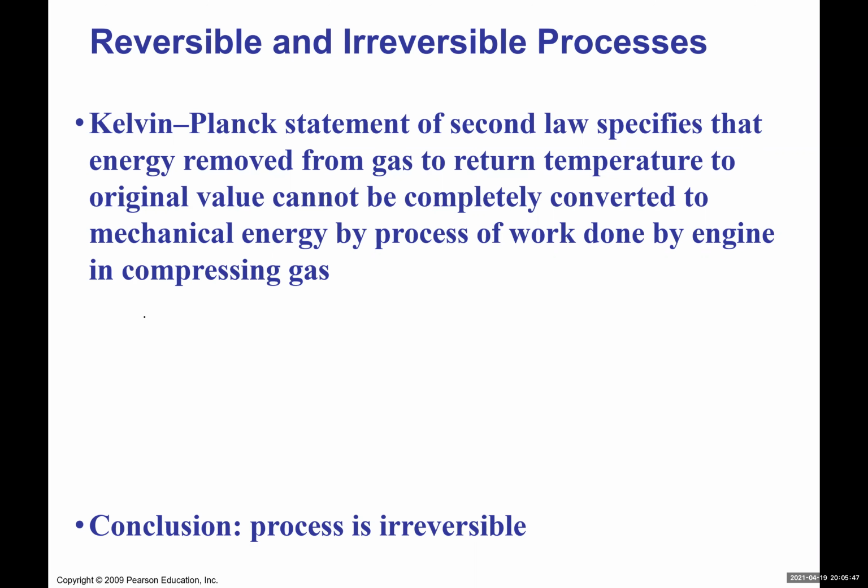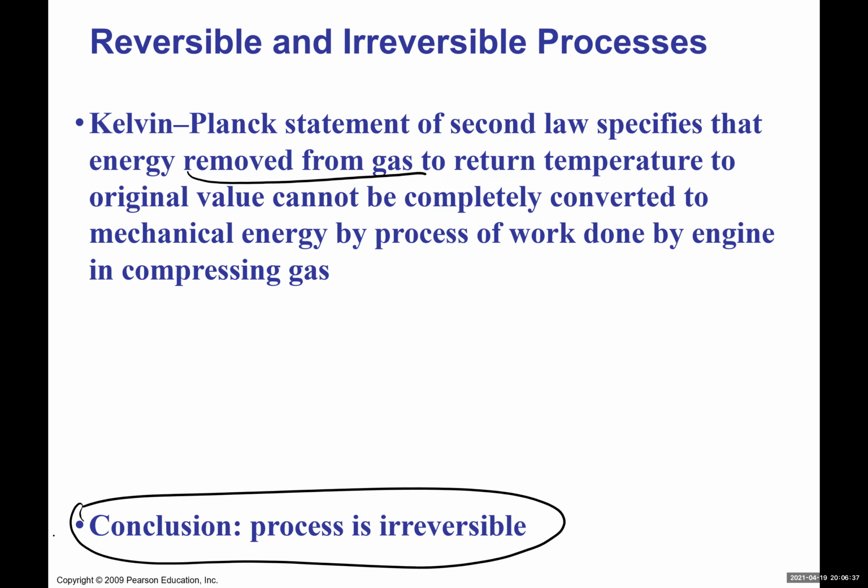That means when you remove heat from the gas to return the temperature to its original value, because when we push the piston inward the temperature increases, in order to return the temperature we have to remove heat. But once you remove it, you cannot completely convert it to mechanical energy by a process of work done by the engine in compressing the gas. That means how much work you do and how much heat is added are not the same. Once the energy goes to heat, some of the energy cannot be converted back. So the conclusion here is that the process is irreversible. All right, so this is again the Kelvin-Planck statement of the second law.